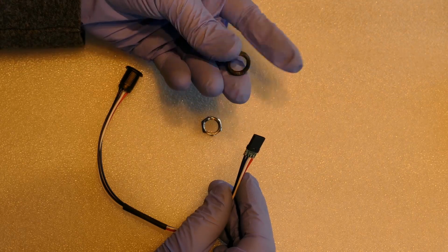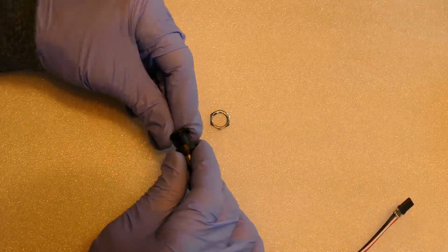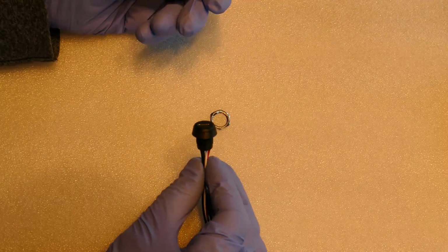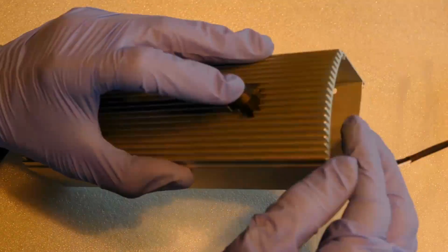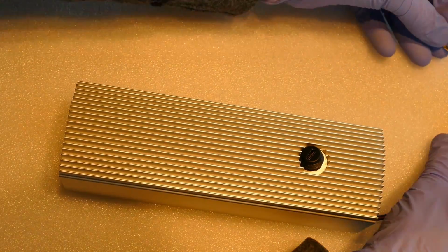In retrospect, the USB jack was a bad choice because it's not fully compatible. It doesn't work if I plug it into a Type-C jack on a computer. However, it does work if I plug it into a Type-A jack using a USB-C to USB-A cable. I did try all the different resistor combinations on the male plug, but I couldn't find a compatible combination.